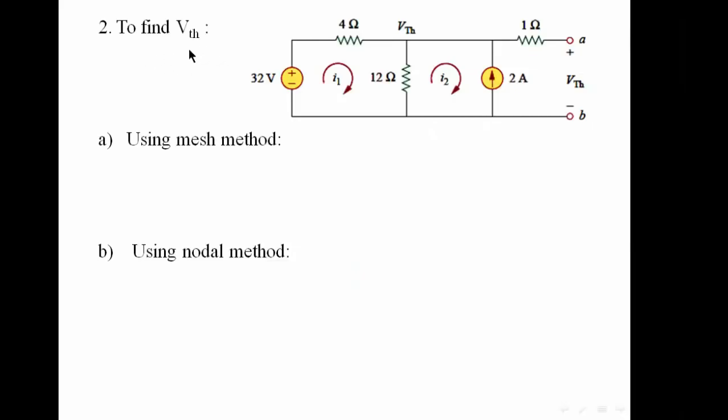Now, we are going to find the Thevenin voltage. V Thevenin is the open circuit voltage in the location of the removed load. We can simply cancel this resistance because there is no current flowing in this resistance, because this terminal is an open circuit. We can see that V Thevenin is parallel to the voltage here, and that's why we call the voltage here V Thevenin.